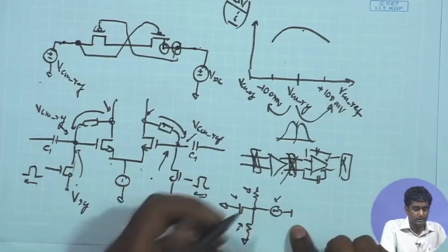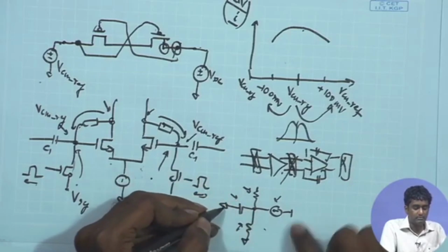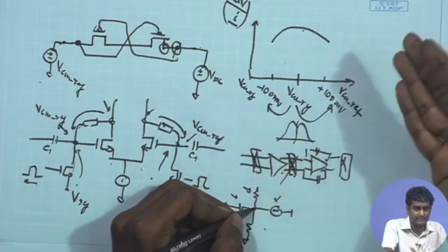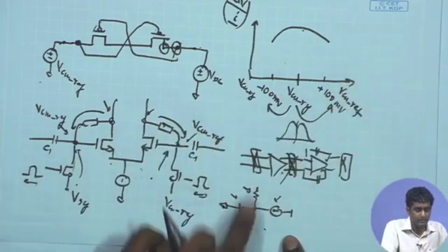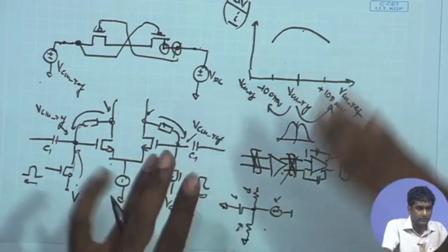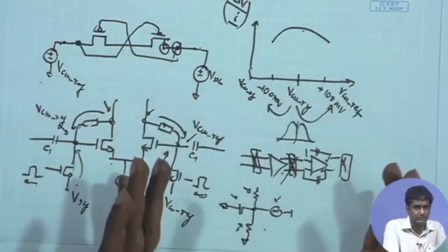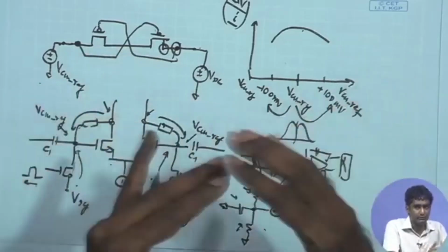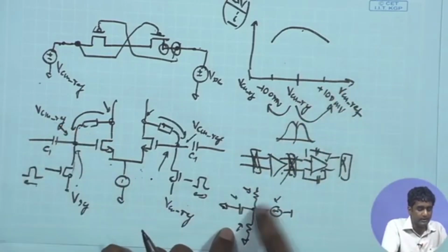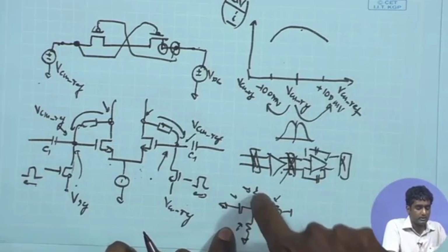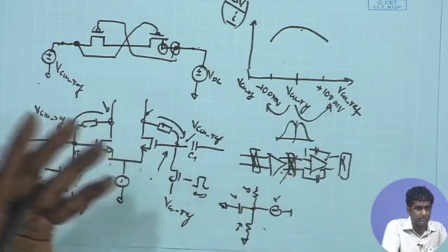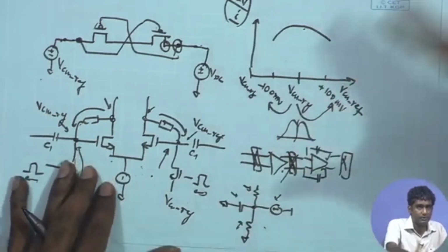As a result, taking the previous step values of the voltages at different nodes, it will try to solve the KCL for the next time step, taking the current values and again finding the resulting voltage. And likewise, ultimately it forms a matrix of all these nodes. When you solve KCL for a large number of nodes, ultimately it is in the form of a matrix, and it solves that matrix for every time step while updating these capacitance values and resistance values, which are bias dependent or voltage and current dependent. So every time step it will keep solving that matrix.